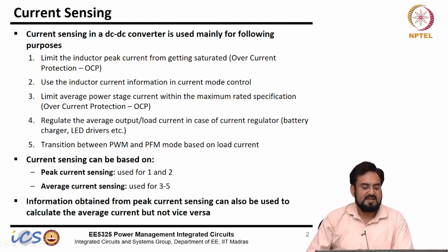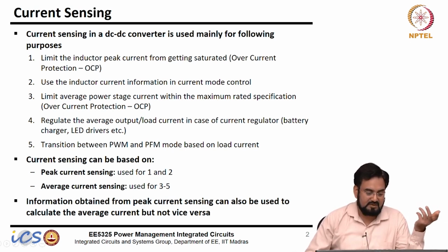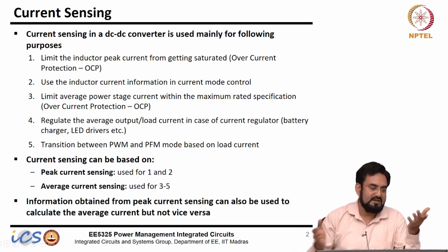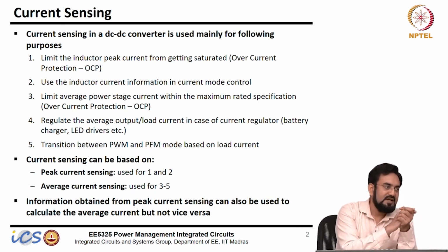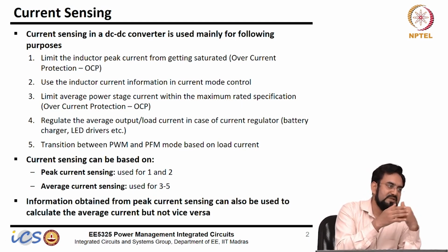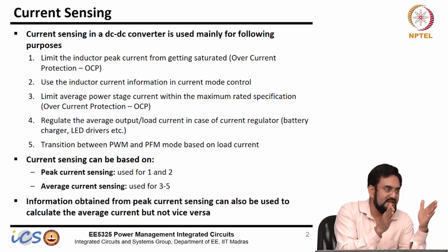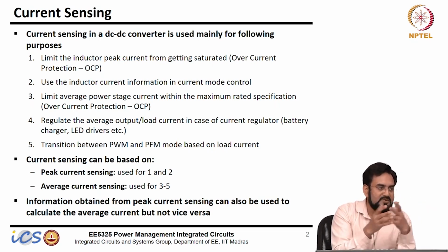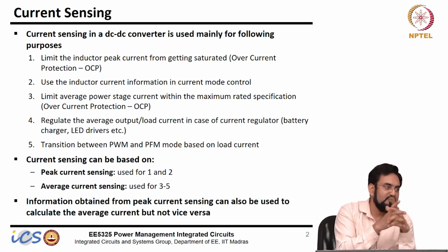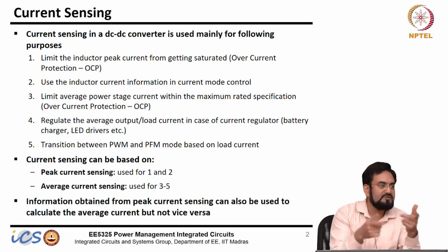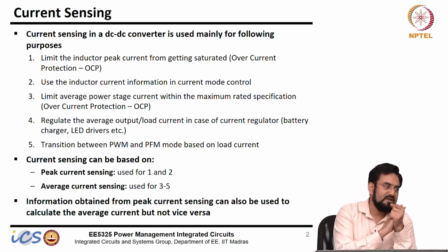Then another place which may or may not require it, depending on how you build your PFM mode. We talked about how you enter PFM mode. One is you can detect a light load condition, or you can always detect the DCM mode, and right away when you enter the DCM mode you can enter PFM mode, or you can wait until your duty cycle is saturated. These two do not require current information. You know when the duty cycle is saturated, and you also know when it's entering DCM.